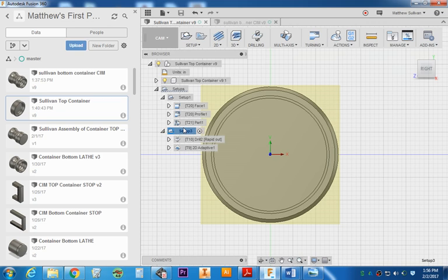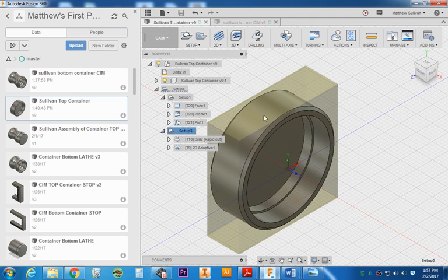If it isn't, you're going to have to make changes. It will not run on the CNC machines, period. It won't run. You will not have a good part. It just won't work out. It'll be cutting out in space. It won't know where your WCS, your work coordinates, are for all your positions.